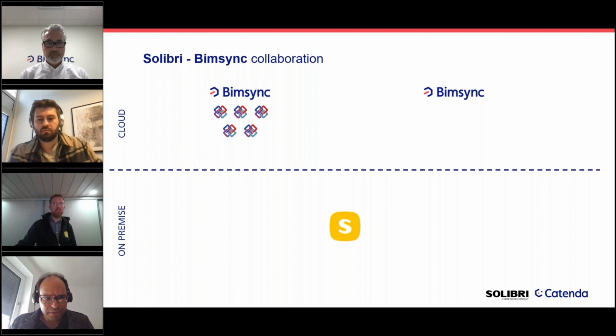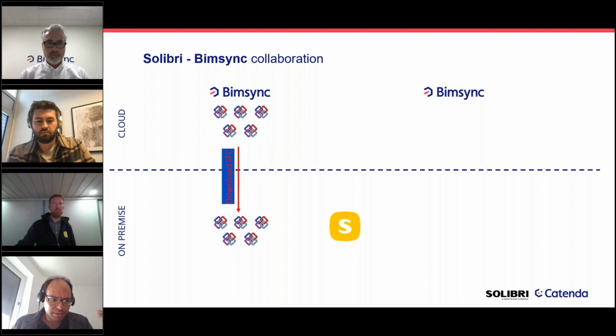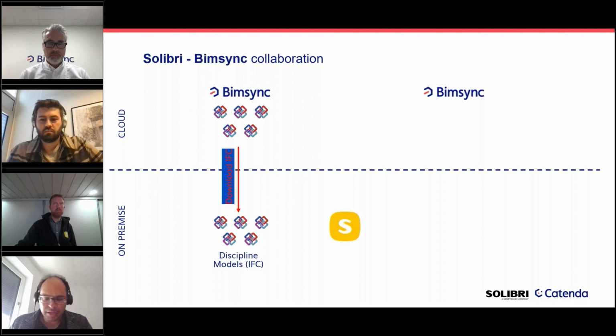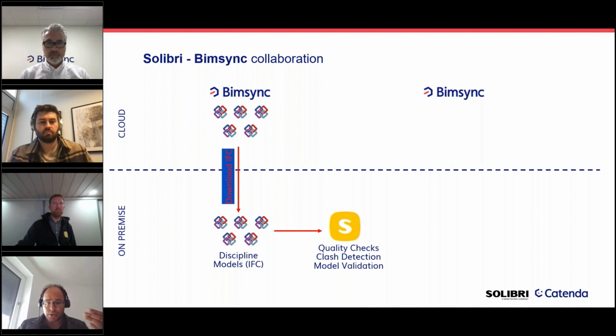So the models are uploaded, they then get downloaded onto an on-premise folder with the different IFC disciplines. There's, for example, the architectural model with the structural model and MEP model. These are then sent into Solibri, where you actually do your quality checks.